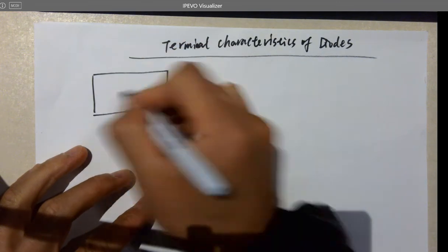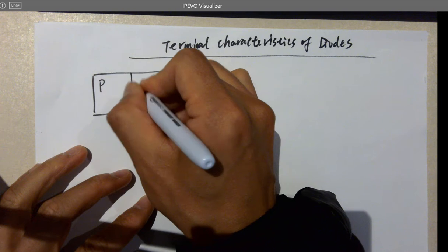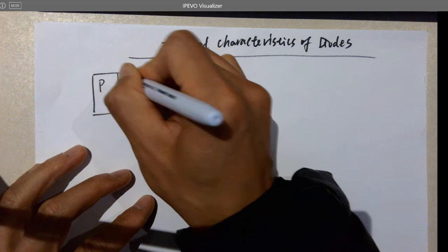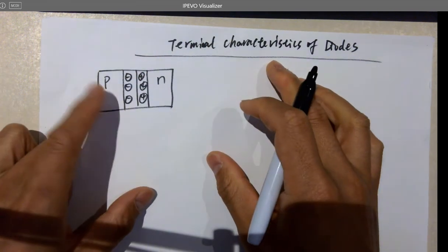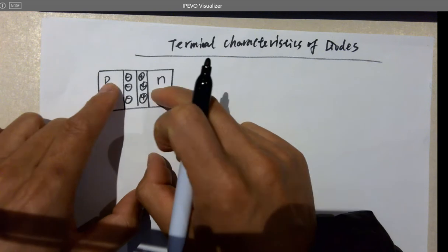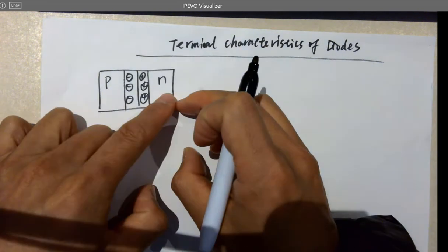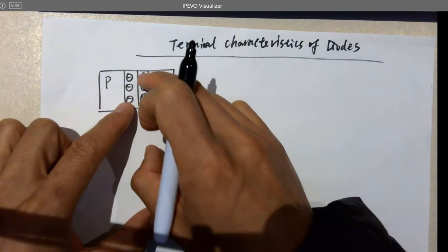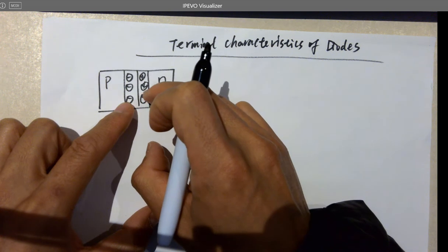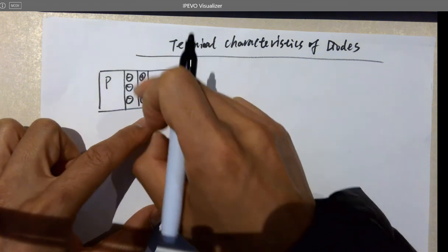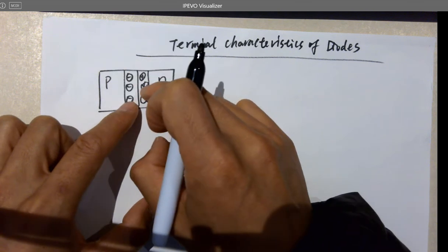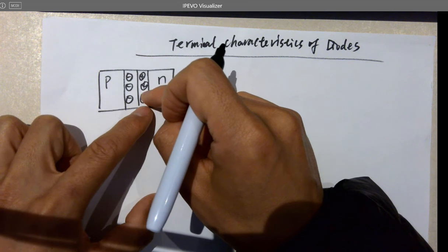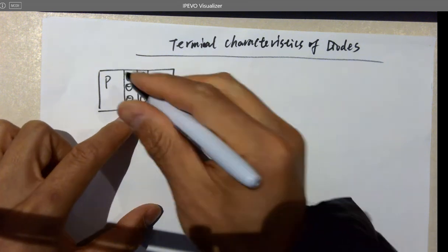Okay. So this comes from the PN junction and the diffusion layer as well. Since we know that this carries more free holes, this carries more free electrons, there's a concentration gradient, so the holes will diffuse to the right hand side and the electrons will diffuse to the left hand side to neutralize the holes, and the holes will neutralize the electrons and also has more left after that neutralization. So that's why this depletion region, both of these two regions are depletion regions, but the right half is positively charged and this is negatively charged. So it forms an electric field.